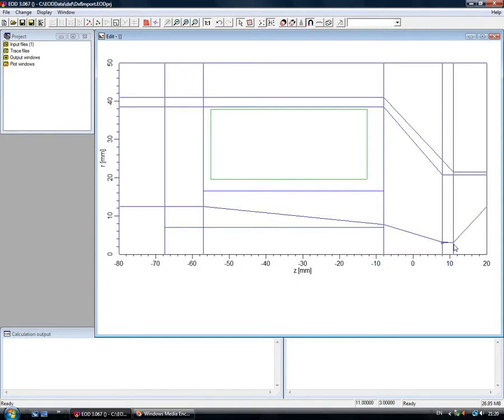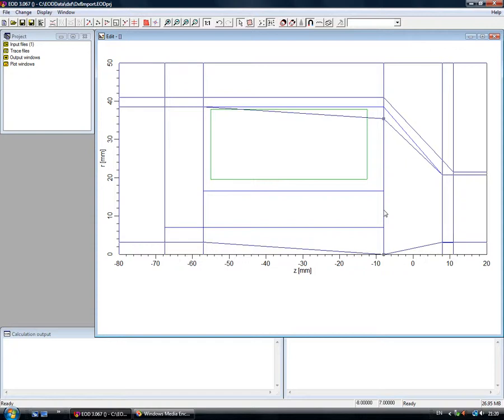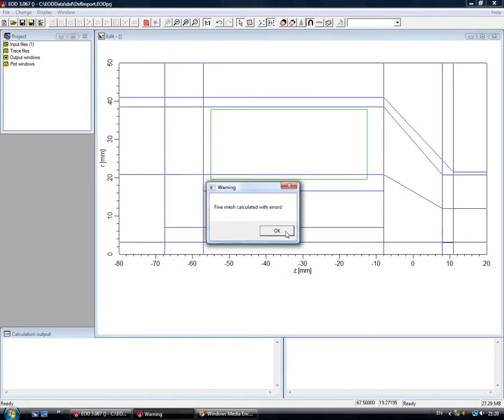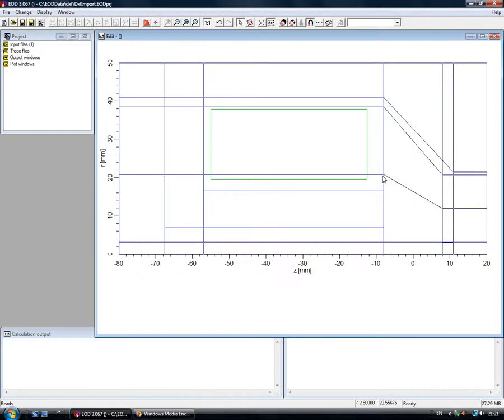Now it is time to look at this point. Because near the axis it's the best choice to have a square fine mesh, we will put the line parallel with the optical axis. Now we will need to create some other horizontal mesh lines. Now I click to select two points, but this point accidentally moved, which I didn't intend, so I can use undo last operation and the points are returned to their proper positions, and now I can create some mesh line and put it in the proper position and align it.